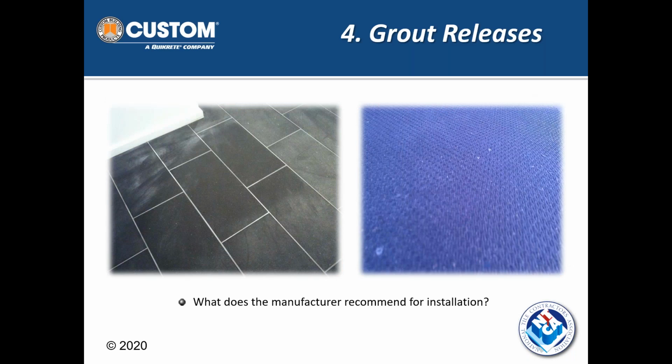So what does the manufacturer recommend for installation? Again, something we want to talk about. Some manufacturers do go into detail about what they recommend for pre-sealing or the use of a grout release. Now here's a good shot of a commercial job where the picture on the left shows obviously a lot of haze. What is that? It's not dirt, that's actual grout haze.